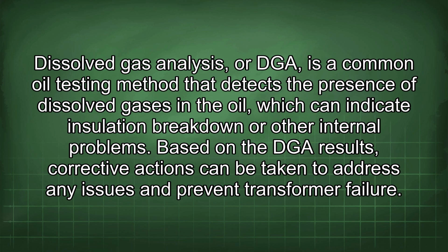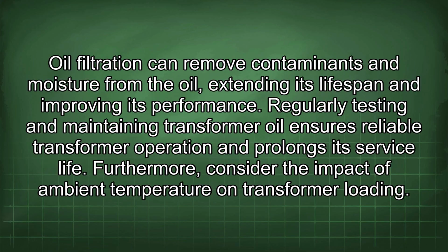Based on the DGA results, corrective actions can be taken to address any issues and prevent transformer failure. Oil filtration can remove contaminants and moisture from the oil, extending its lifespan and improving its performance. Regularly testing and maintaining transformer oil ensures reliable transformer operation and prolongs its service life.